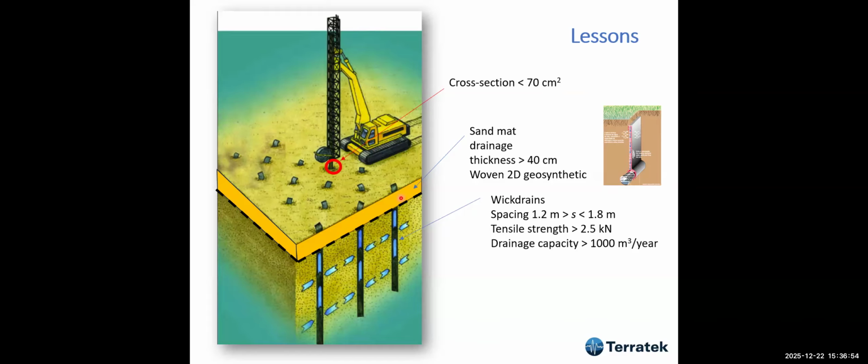So in order to get rid of that, since these drains, the equivalent diameter should be close to 100 or 80, something like that, the idea of having this minimum space of 1.2 is a good one. Perhaps you can go 1.1, but I've been to a project which they used 0.9. I'm not very happy with that, but I don't have the results of that project.